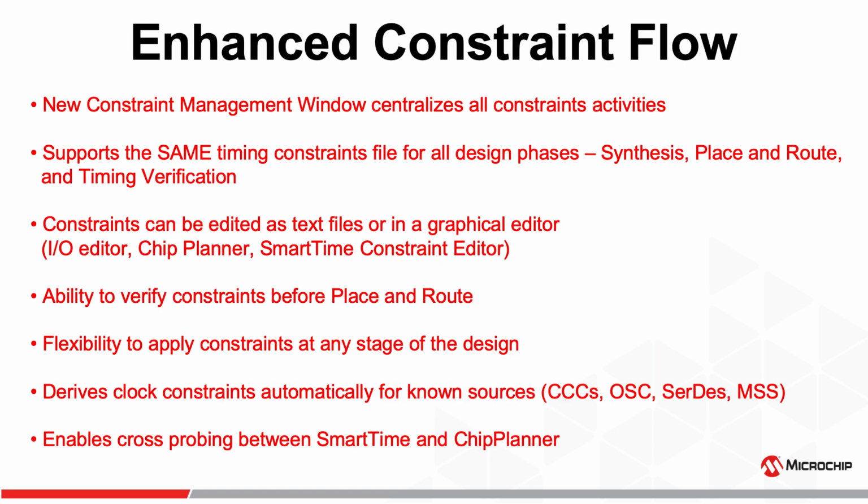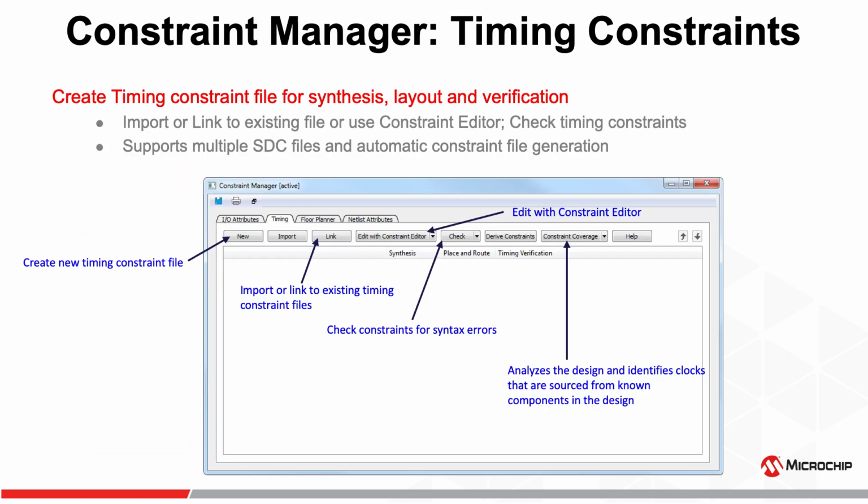Most of the points I covered in the previous slides. The main thing is the enhanced constraints flow tool is a centralized tool used to apply all kinds of constraints in a single UI. Like I mentioned in the previous slide, you can apply the IO constraints, timing constraints, chip planner constraints, the FDC, NDC, all kinds of constraints in the single tool. And you can also verify the syntax using this tool itself before even going to the implementation part. That actually saves time for you. So instead of